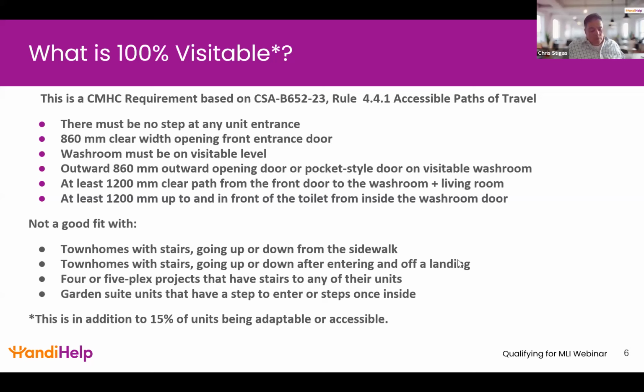And then the last one is 1200 millimeters up to and in front of the toilet inside the washroom. So from the tip of the toilet bowl to the opposite wall, 1200 millimeters. In some circumstances where you might be close and you get to like 1100 or 1120 or 1130,